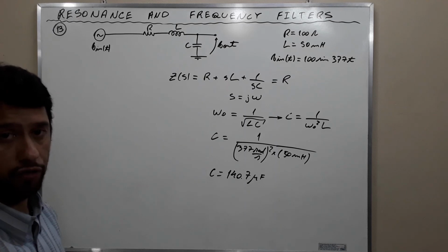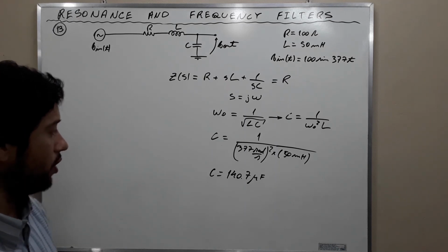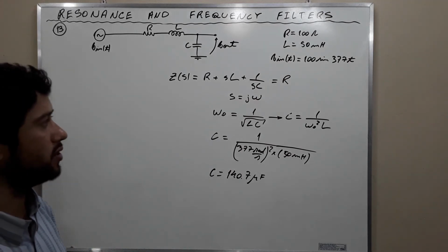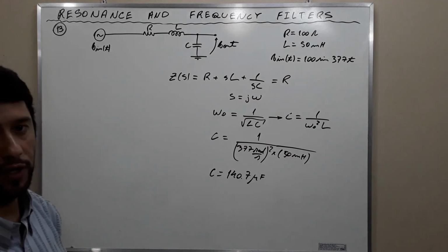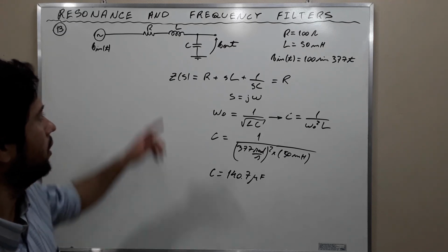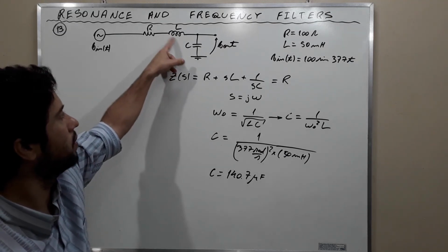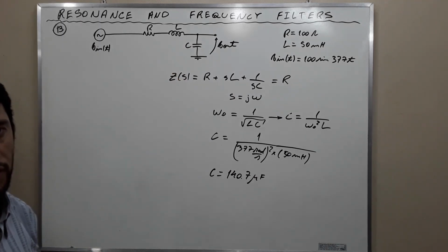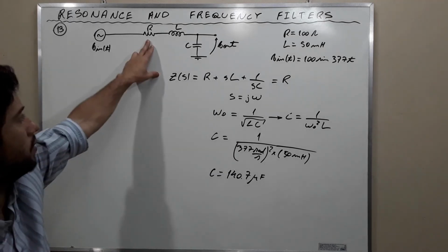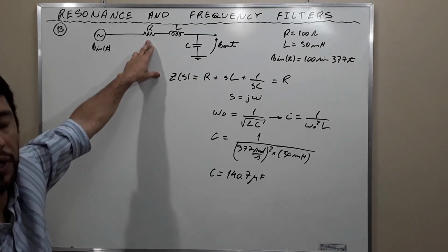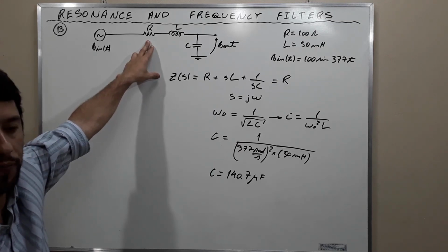We wished this. We wanted then the capacitor and the inductor to resonate precisely at the frequency of the power supply. When it happens, they act as a short circuit. They cancel each other out. They cancel their effects. And the equivalent impedance becomes purely resistive.